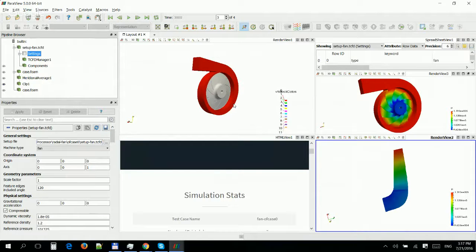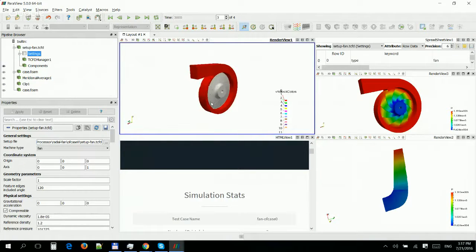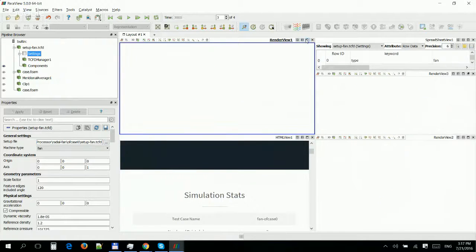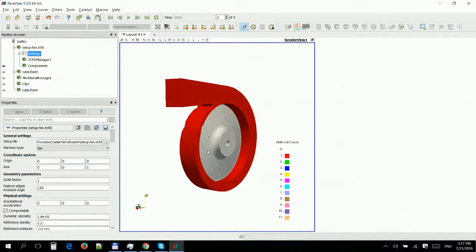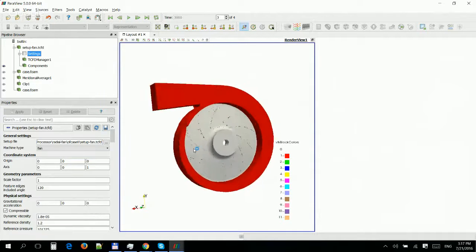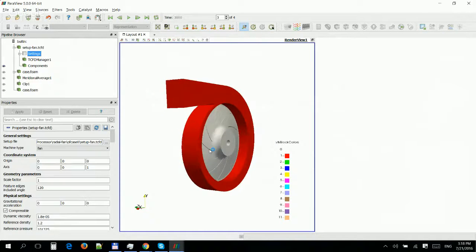Okay, the surface model. The surface model is a simple CAD model in STL format. It can be combined from multiple components. Any number of components is allowed. There can be an inlet tube, outlet tube, the volute, impeller, et cetera. Each component should be watertight, and ideally it should fit vertex to vertex in the STL file.